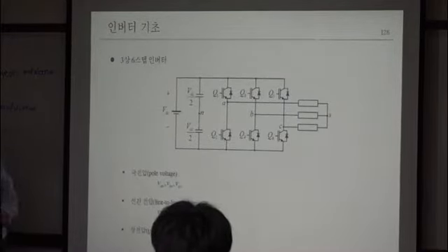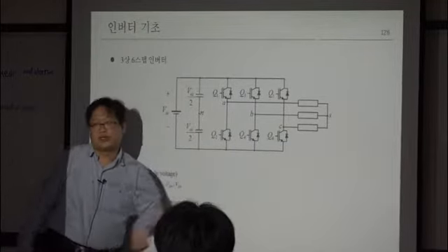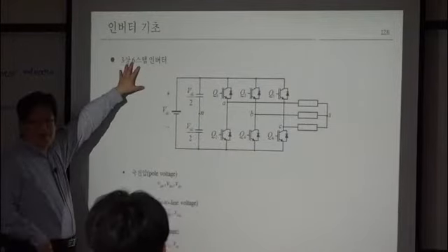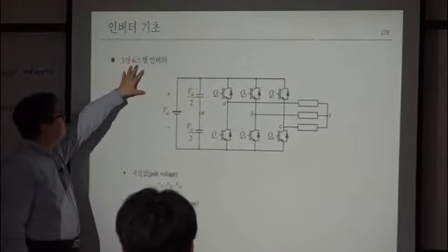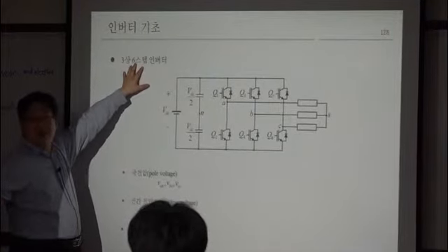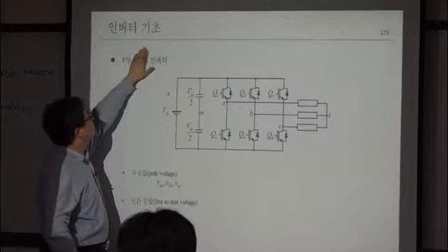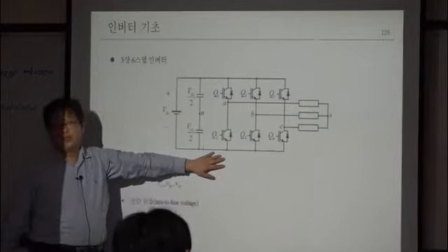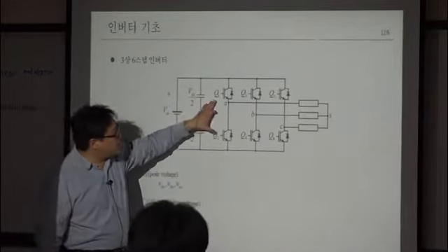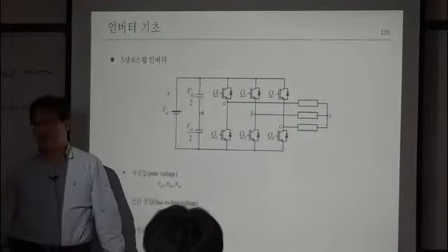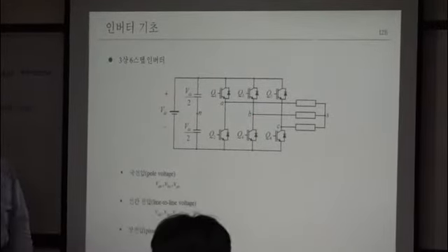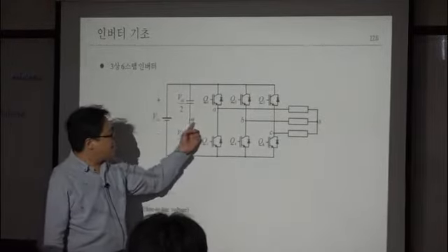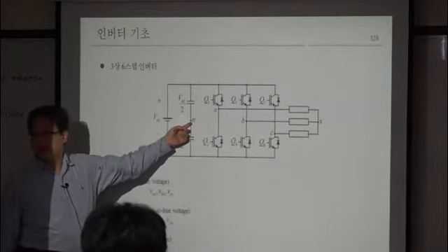Then, let's see this inverter. This is the 3-phase inverter, and the 6 step depends on the modulation strategy. But you can just simply ignore that here, and this is the structure of the three-phase inverter. A three-phase inverter has what, three half-bridge inverters, and we need to define some voltages. The first one is VAN, VBN, VCN. Those are pole voltages, right?